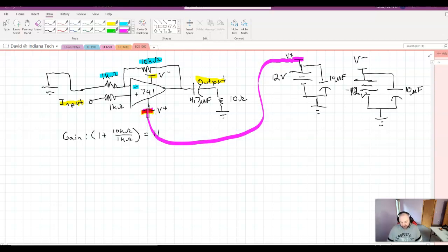So that V bar actually makes that connection. And this can help because imagine if you had 20 chips and they all needed a 12-volt power supply on them. Instead of having to wire them all up to a 12-volt battery, you can just say V plus and have one set up at 12 volt and then put this V plus with this bar thing for all of those power supplies.